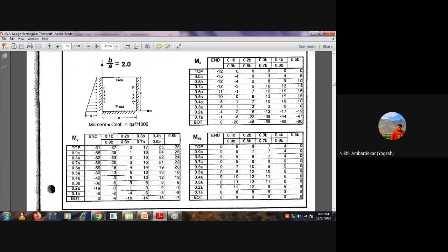Maybe it is subjected to a live load of 5 per square meter, or maybe 3 live load. What will that be? It's like a UDL, so you don't need to consider the triangular pressure. Just go for the rectangular pressure and you can find the bending moment. But for wall panels, only concrete walls, you cannot apply this to brick panels. If it is on shear walls, yes, then you can design it.